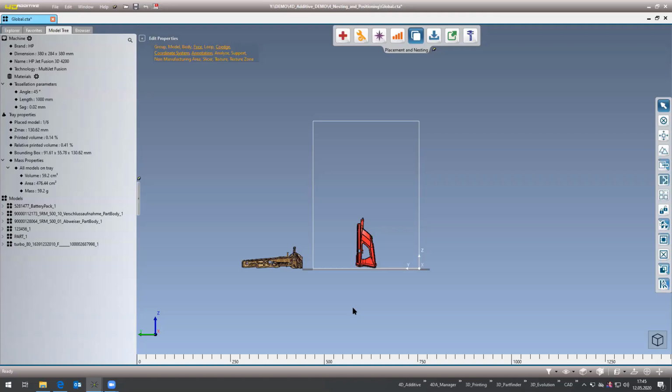Yeah, so we export the support structures. Yeah, they can be included in an analysis. Oh, you can. That is not a problem. With the hollowing and lattice structures, like I said, they are integrated in the tessellated layer. So we would have to export then the original geometry, but in a tessellated format. So if we just export the original representation, the hollowing and the lattice structures will not be in this model. So we would then have to work with a tessellated.